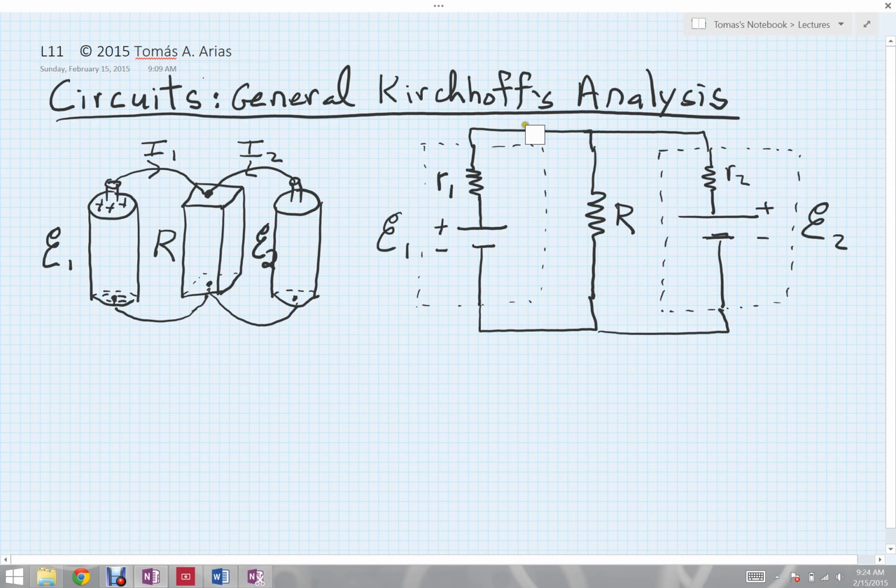You needed the voltage through the series to be the sum of the individual voltages. It looks like that might work, because to get the potential from here to here, I would just add this voltage to this voltage. The difficulty, though, is that in a series combination, you also need the current to be identical through these two resistors. But the current that comes through R1, some of that current, actually all that current, might go through the resistor R, but there's additional current coming in. So the current in these two elements will not line up. So these two you can't think of as in series.